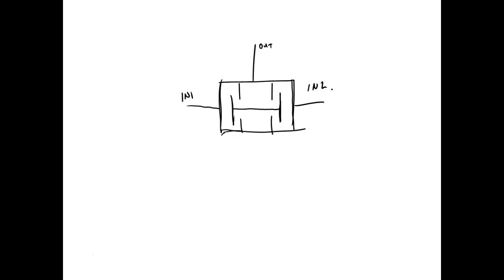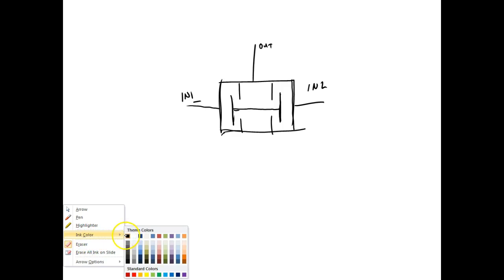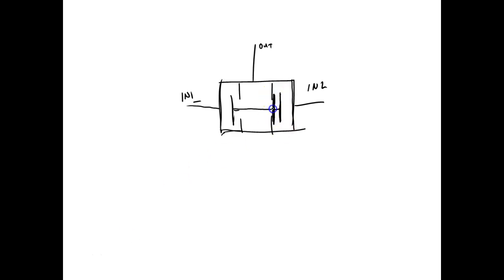We got these over in the drawer over there. So let's say I put pressure on this side. What's it going to do? It's going to cause this spool to come over here and block it off, and I'm not going to get any output pressure. Right? If I come over here and put pressure on the other side, what's it going to do? It's going to come over here and block it off, and we're not going to get any output. Y'all understand so far?